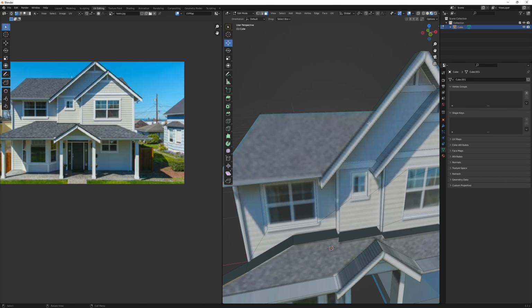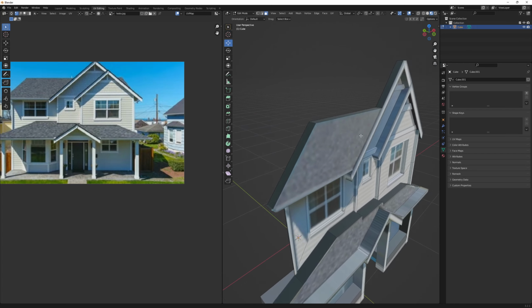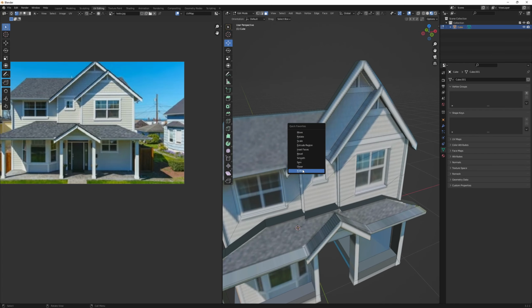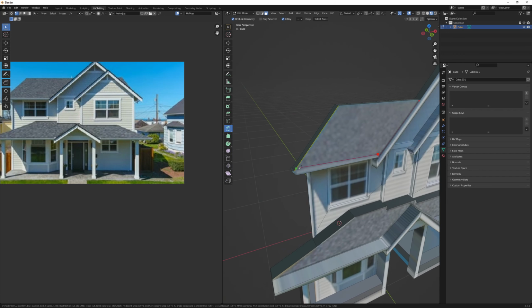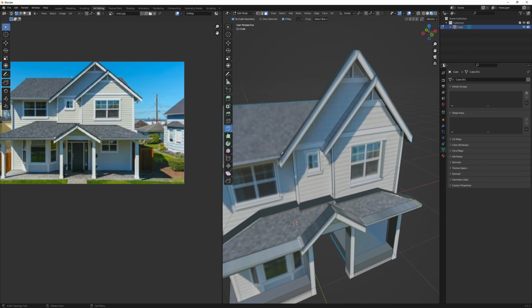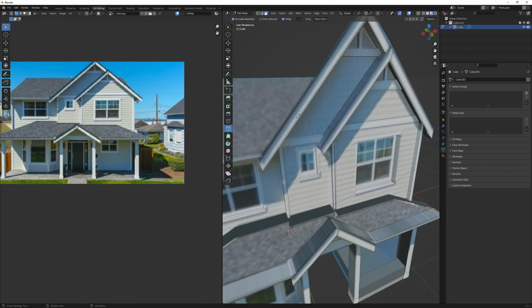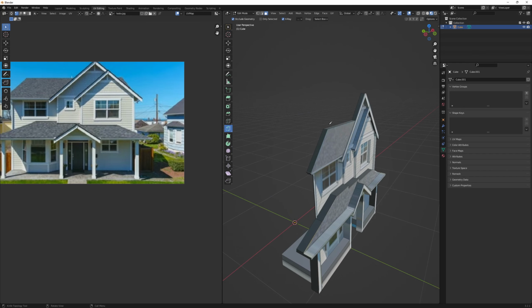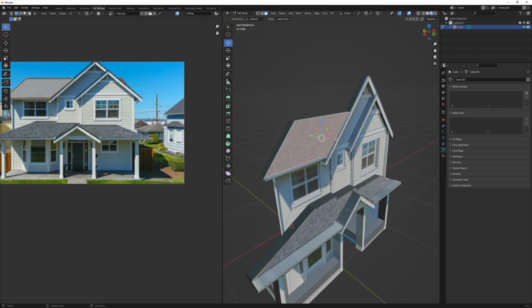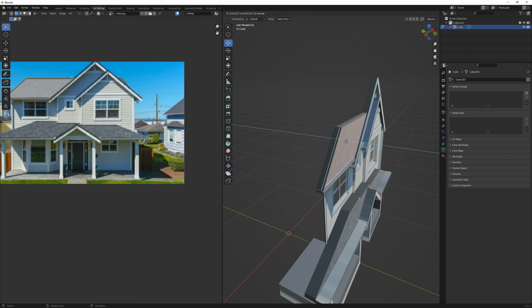We can see here where this building needs to be pulled back. So what I'm going to do now is go in with the Knife Tool. I'm just going to follow this apex down here, all the way over to the end of our roof tile here. Now what I can do is select our thing and just extrude it. No, not extrude it, sorry.